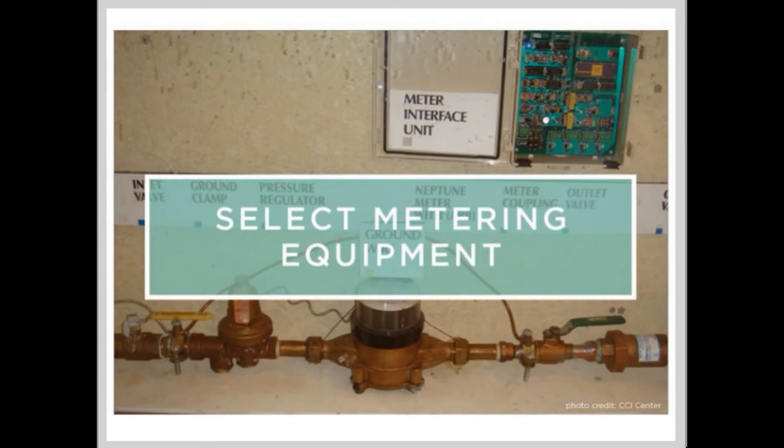The project team should choose a submeter type if no existing meters are present or if existing meters need replacing. Submeters may be manually read or connected to a building information system. The meters may be equipped with data logging capability independent of a building information system. If meters are to be read manually, project teams should consider digital indicators, which may reduce errors in recording. Wet meters will likely be the most cost-effective approach. However, clamp-on meters may be simpler to install.